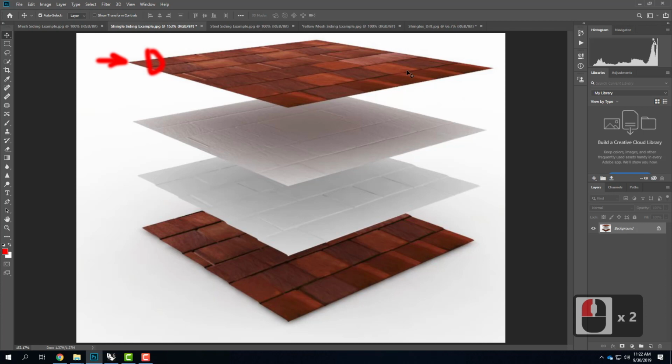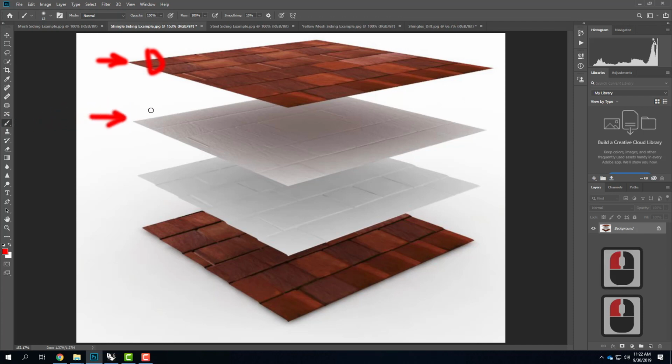That's the photograph. It's a tiling texture. The next piece down here is something that's called a bump map. And that gives us small grain texture, things like the wood grain itself. So it's little stuff on the surface, because not all surfaces are perfectly smooth. They always have a little bit of texture to it. That's what the bump map does.